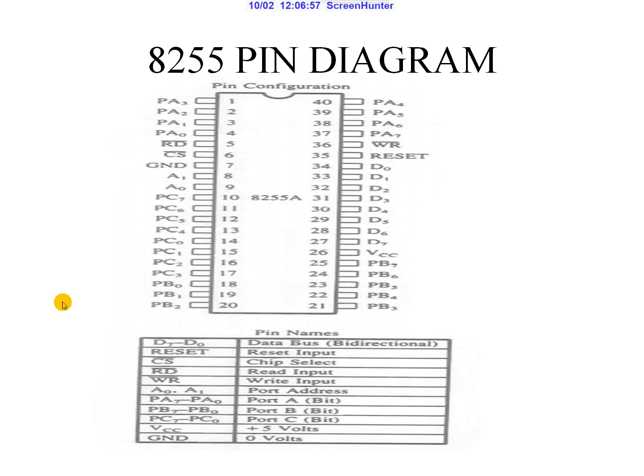In order to control the operations of the 8255, we have the control pins: read, write, and A0 and A1, which are used for choosing the port addresses. Whether we are going to use port A, port B or port C, we choose by using A0 and A1.